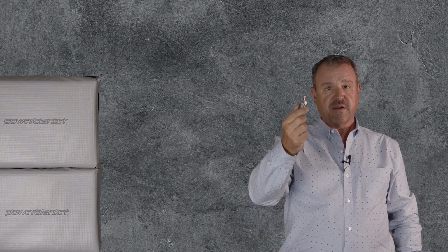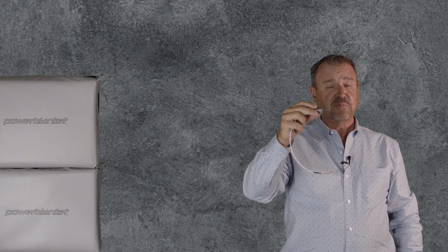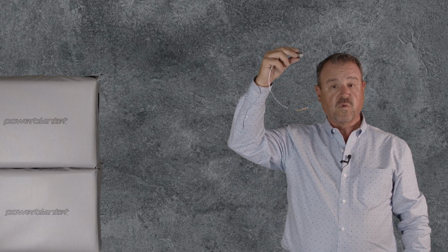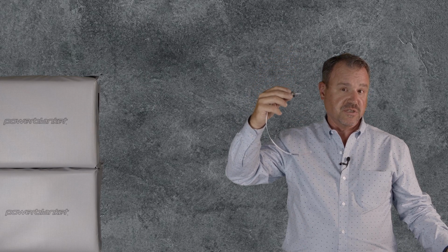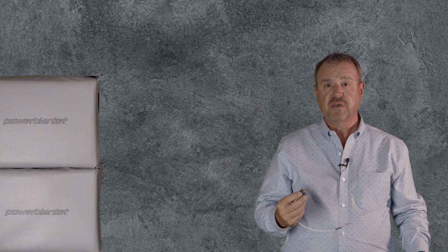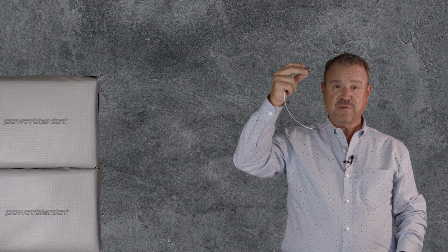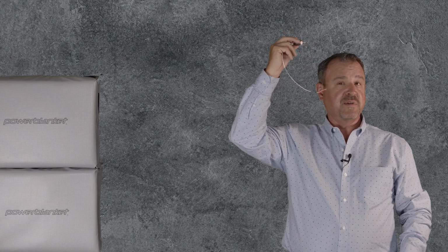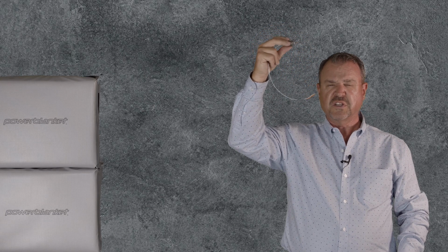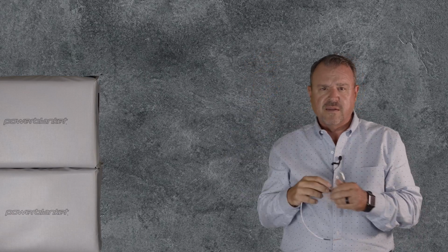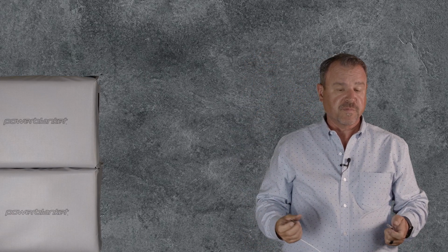This is an ambient air sensing thermostat that's designed to be put into standard hardware. It senses air temperature outside. So in a typical heat trace application or a freeze protection application, when it sees, say, a temperature of 35 degrees, it turns the entire heating system on. So this needs to be placed up in the air, maybe on the north side of the plant in the wind in the coldest possible part of the plant, not hidden behind an I-beam or down in a warm area inside of a building. A sensor could also be placed on a pipe.